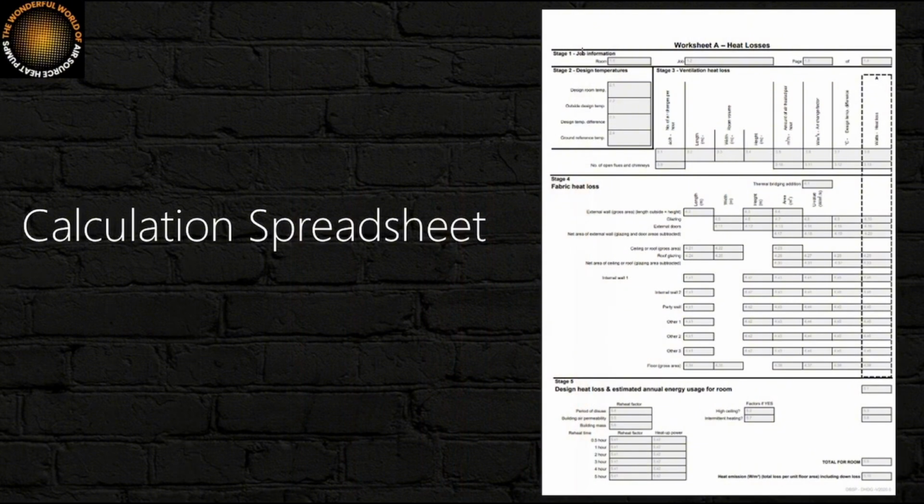Now, in section 3 of the Domestic Heating Design Guide, there is a calculation spreadsheet. Now, it can look ever so daunting when you first are encountered with it. It's broken down into 5 stages, but one of the good things about those 5 stages, each of our boxes have codes in them. Now, those codes relate to a reference guide that I've extracted, that basically tells you the information that's needed in that box. So it is pretty user-friendly once you get your head around it.